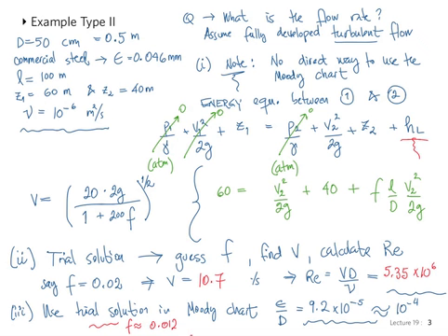I don't understand the use of the trial, because if you're putting in the F as 0.012, shouldn't you just get that back out anyway? Yeah, but we didn't choose 0.012, we chose 0.02, just a guess. So when we looked back in the Moody chart, we were just verifying what we had already seen. But you need to calculate it twice to see that it doesn't change and decide that that's the value you're going to keep. You're creating an outlier for verification.